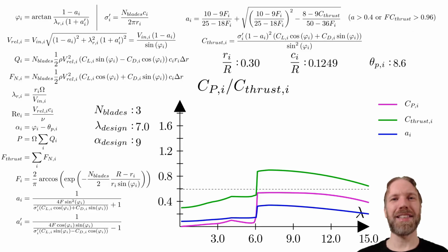I also want to mention that the equations can have multiple solutions, one in stall and one without stall. Therefore, I will add thin lines where I designed the code to look for solutions at higher actual induction factors. We can see a small region with multiple solutions around tip speed ratio 6. Let us go all the way down to segment radius 10%.